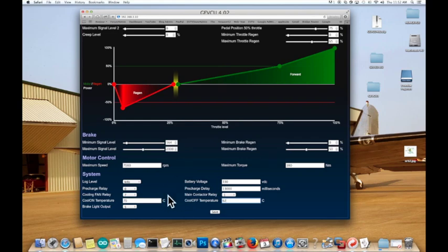Let's leave it on once it hits 70 until it gets down to 62 and take out the hysteresis there. And when it gets all the way down to 62, then I'll cut off that output and turn off my fans. And now if it heats back up to 70, which might take several minutes, then it'll come back on. So now they'll come on and go off as needed, but on a much slower cycle. And you can set this to whatever you like to moderate that cycle. You may want it to come all the way down to 55 degrees centigrade or something before it turns back off.